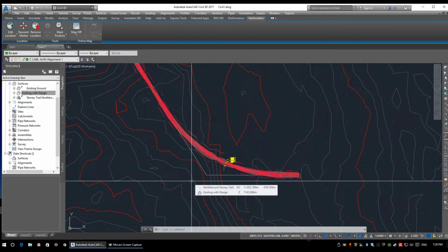Now, when designing our pond, in industry, we would have to go to the government of Canada to acquire some rainfall data. And being that this is just southwest of Calgary, that should be pretty easy to track down. But for this project, we're just going to concentrate on a pure volume. So we're going to try and design a pond that holds, we'll say 10,000 cubic meters of water.